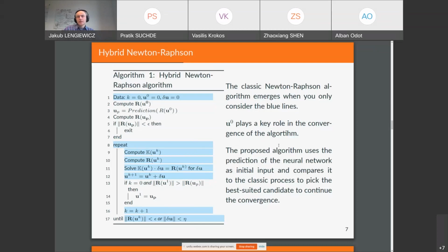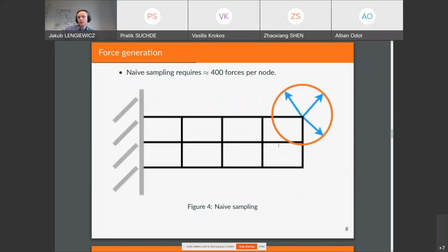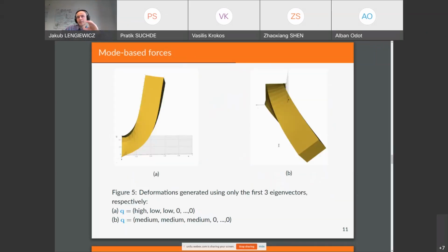I see. All right. Yeah, and I think this is especially suitable for the cases which require a multi-step loading procedure for your finite element method, because even for hyperelasticity, for some loadings or some problems, you need to have a multi-step loading in order to reach the final deformation, which can be very big.